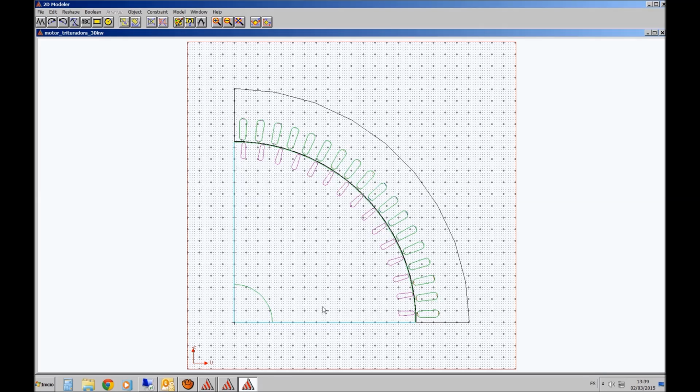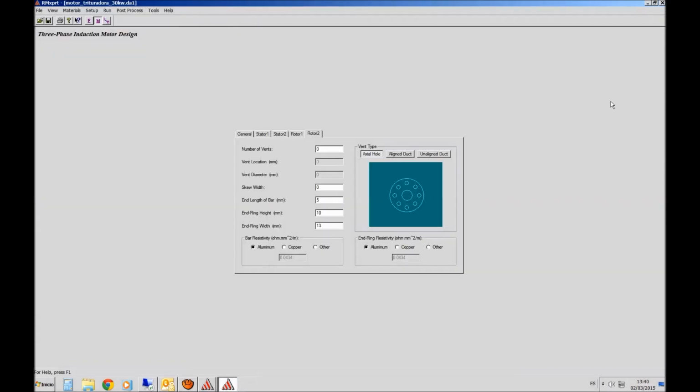So if you want to play with finite elements, much better to play with the complete model I will give you. But well, you've got a tool, and you know you can work with this. It's an approximate section that then you will define materials and you can analyze by means of finite elements, and you create a Maxwell 2D project, and you can also use another tool called Simplorer, but it is not installed in this version. So let's go now to performance curves.